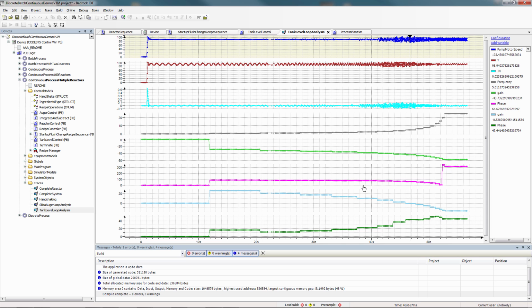The loop bandwidth is where the total gain around the loop is 1.0 or 0 dB. This occurs at 5 Hz. The phase margin is the phase at the loop crossover frequency, which is 43 degrees. 43 degrees of phase margin will provide an underdamped loop response and will exhibit ringing in the time domain.